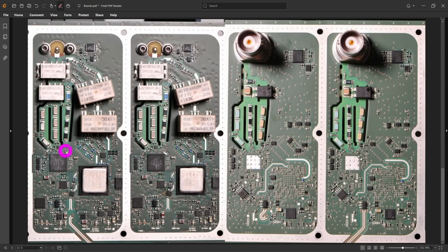At the same time, very low noise, 130 microvolt at the 1 millivolt per division, again at full bandwidth of 2 gigahertz, not easy, and you get to apply a 5 volt plus or minus offset to the input even at the 500 microvolt per division. Now you can imagine that that can be pretty helpful because you sometimes have noise on top of a signal with a fairly large DC value, and you can absorb that directly in the front end of the oscilloscope, saving you a lot of probing and other complications.